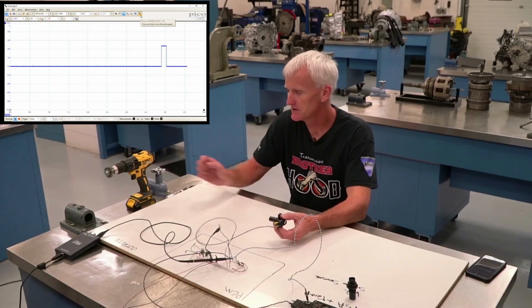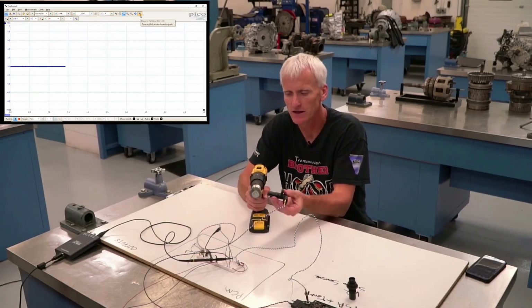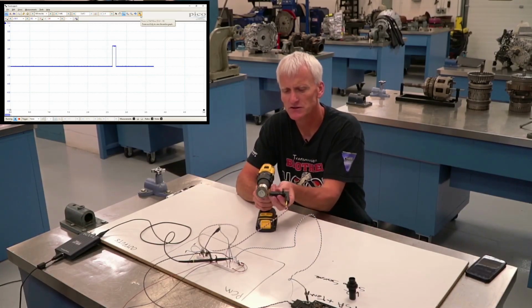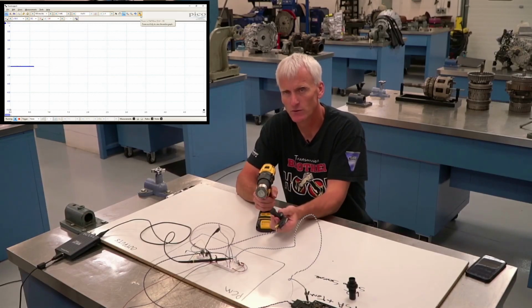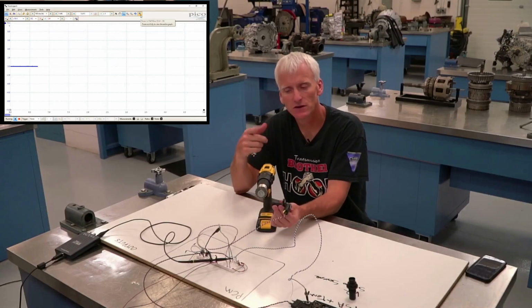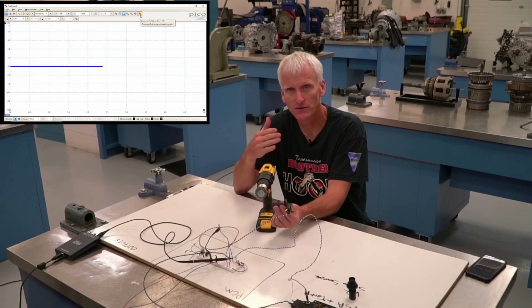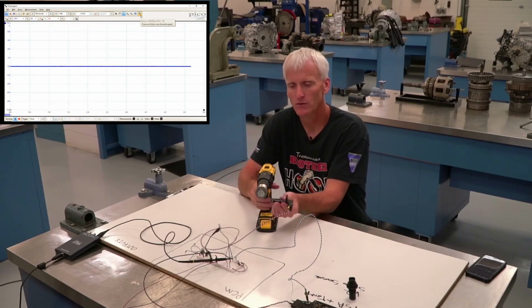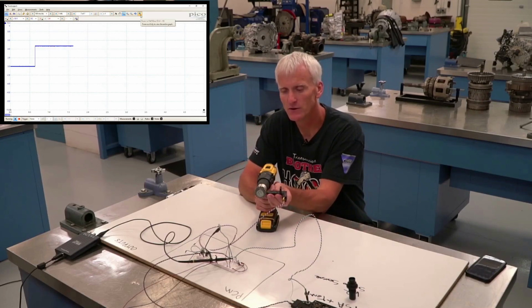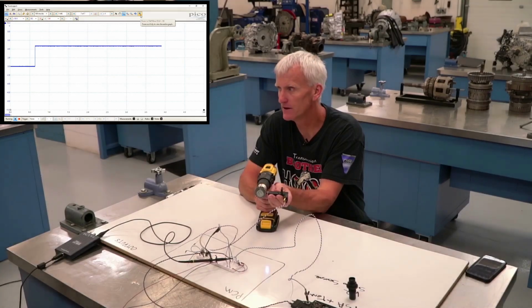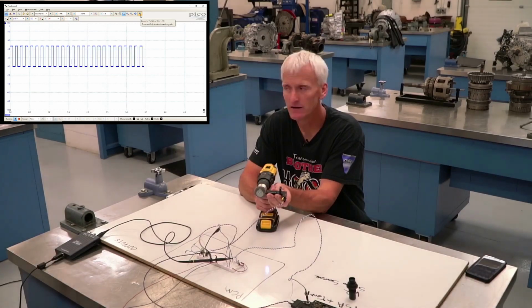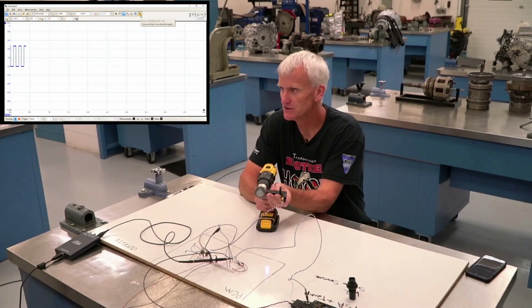One of the benefits of this Hall sensor is that we can measure slow rotation. With the variable reluctance sensor, if it's going slow, the flux lines aren't changing fast enough to induce a lot of current into those wires. So we don't actually get much of a voltage change. It requires some RPM. Whereas this Hall element, we can go slow. You can see right there, if my voltage is high, I'm moving this really slow and you can see my square wave pattern is changing. And the faster I go,